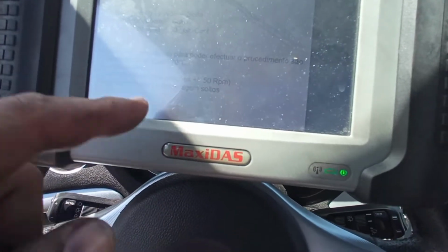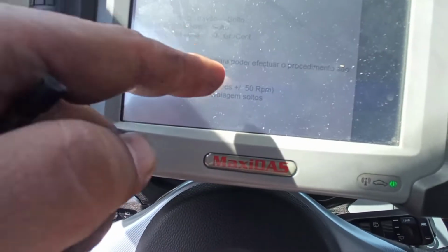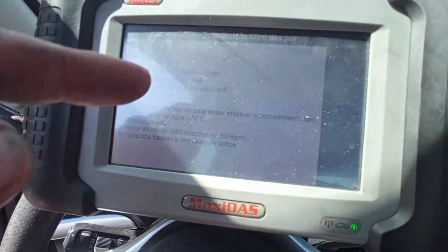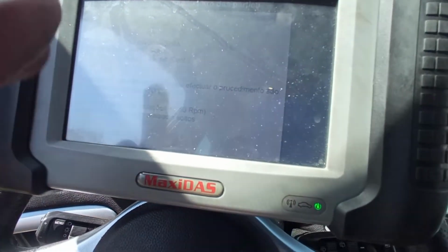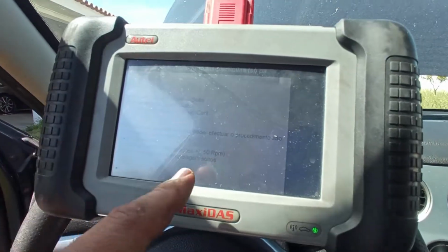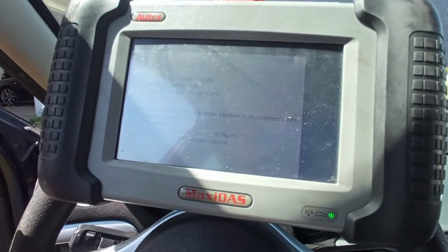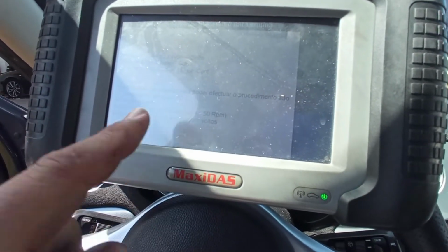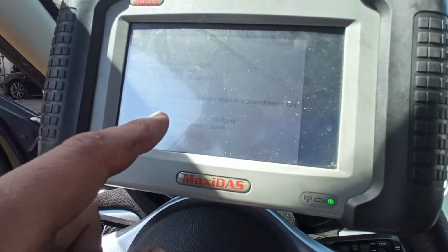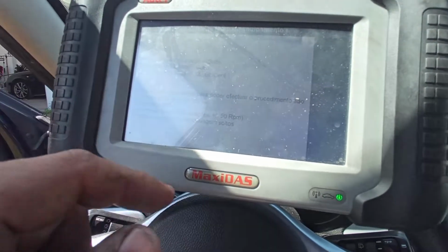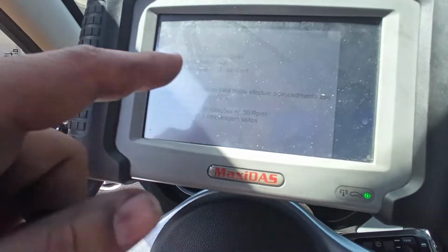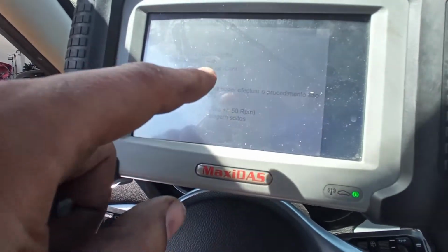I will wait on idle. Well, the car is waiting on idle for the temperature to reach the 70 degrees to do the okay or not for the DPF, because a new DPF, if it has a malfunction or is not clean well enough, the car will say, no, that DPF is not okay. Even though you are telling me, oh yes, you have a new DPF. No, I have not. Please give me a correct DPF. So I'll try to do that.